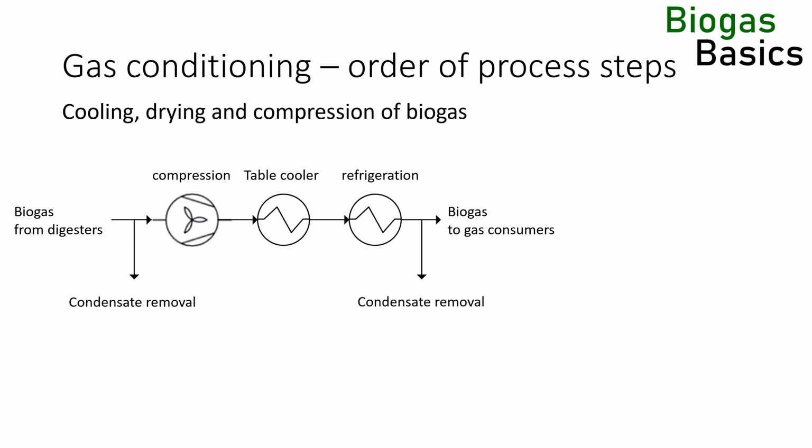A two-stage gas cooling system is state-of-the-art in biogas plants and provides energy savings compared to a single-stage refrigerant cooling system. More condensate is removed after the second heat exchanger. The produced biogas is saturated but at a low temperature. Nevertheless, it can still form condensate in downstream pipelines if the ambient temperature is below the brine temperature.